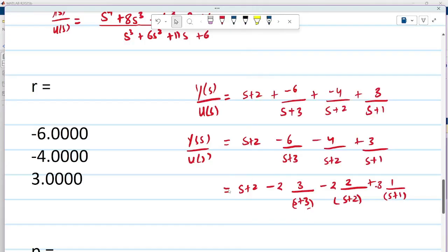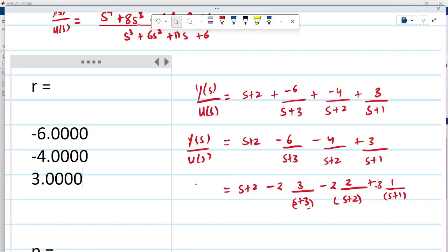So the only thing you have to do in the inverse Laplace transform is just try to get some fractions similar to the ones you have in the table, so that you can directly transform them into the time domain. So this is how you can perform the Laplace transformation of the partial fraction of a system, and find the transfer function and perform the partial fraction using MATLAB. So next we can deal with second order systems.